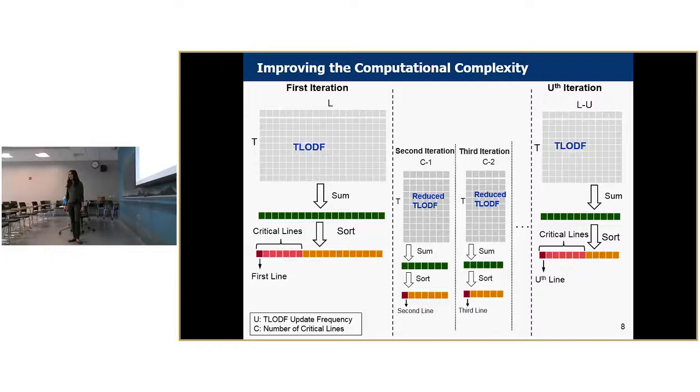The little dinky ones you wouldn't care about, so you could actually have a pretty small number of lines. For example, for the 2000 bus system, you have like 3000 lines, and out of these, you can open up to like 50 lines and you can still reduce the losses. So the number isn't that small, but it's not that big.